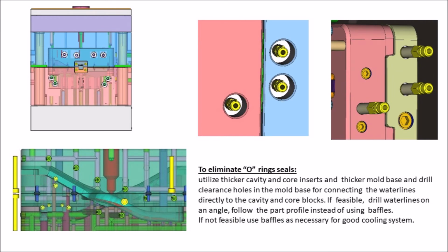If feasible, drill water lines on an angle. Follow the part profile instead of using baffles. If not feasible, use baffles as necessary for good cooling system. The following slides show an acceptable preliminary DFM and mold flow analyses.